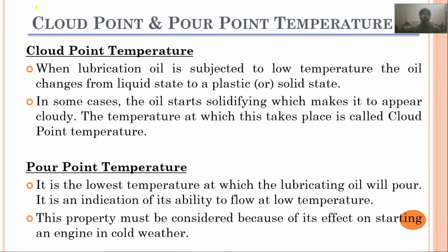Alright, next we have the cloud point temperature. Okay, so here you can see that cloud point temperature is basically this: when we decrease the temperature of a lubricant oil, the lubricant oil will start changing its condition from liquid state to a solid state, and this phenomenon occurs because of the solidification of the wax content in the lubricating oil.